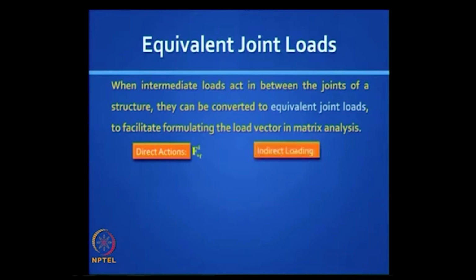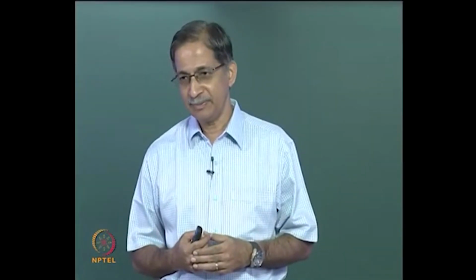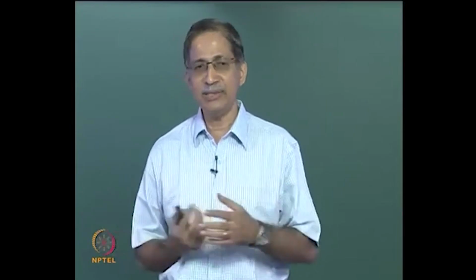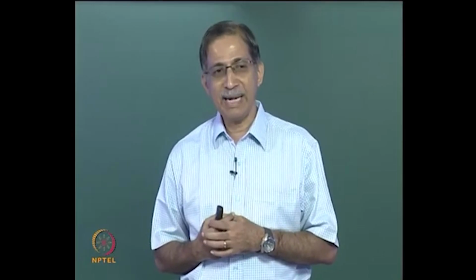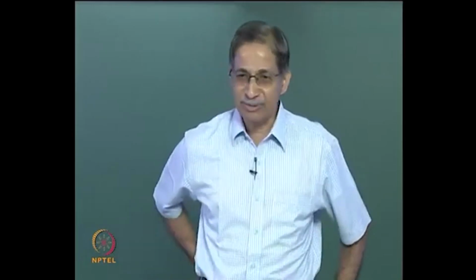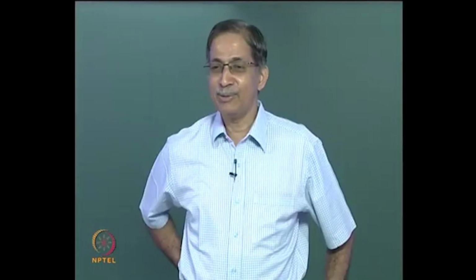indirect loading. Take a truss. Let's say you have a lack of fit problem in the truss, or let's say you have a temperature change problem, okay, that's indirect loading. How will you handle that? How will you convert it to fixed end forces? How will you find that tension? Where is it? Let's say it's statically determinate. Then why are you taking that as a fixed end force?